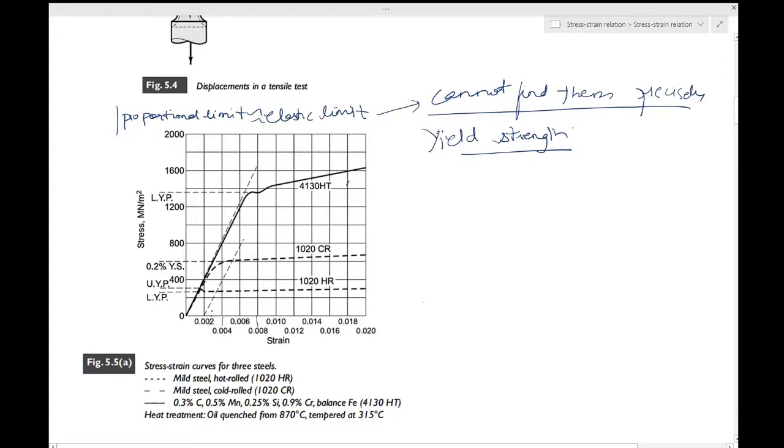And as I have said before, the plastic deformations normally are much larger than the elastic deformations. I think it's written somewhere in your textbook that it's around 100 times more than the elastic limit, just as an example. So it is fine to ignore that 1% of the plastic strain which is of the same order as elastic strain. You don't have to worry too much about all that, and hence it is okay to find a quantity called yield strength.